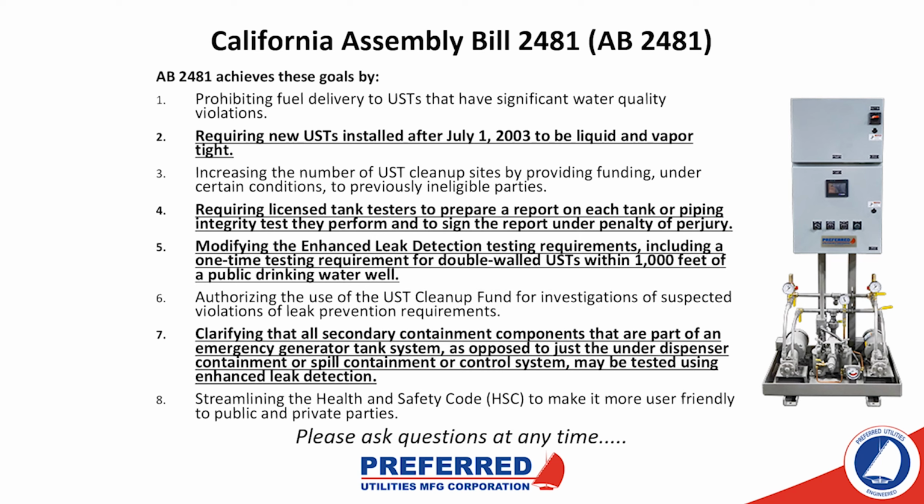Makes sense. Number 5, modifying the enhanced leak detection testing requirements, including a one-time testing requirement for double wall USTs within 1,000 feet of a public drinking water well. These requirements of the enhanced leak detection, or ELD, have actually changed over the years. They're a little bit simpler now. They can just do a pressure pipe test.